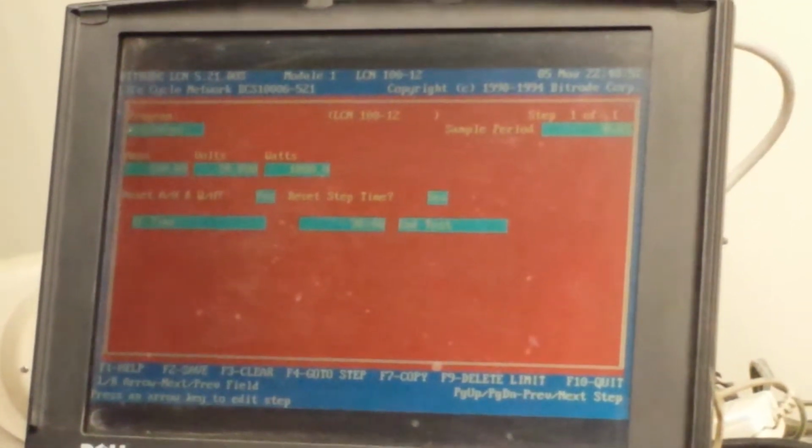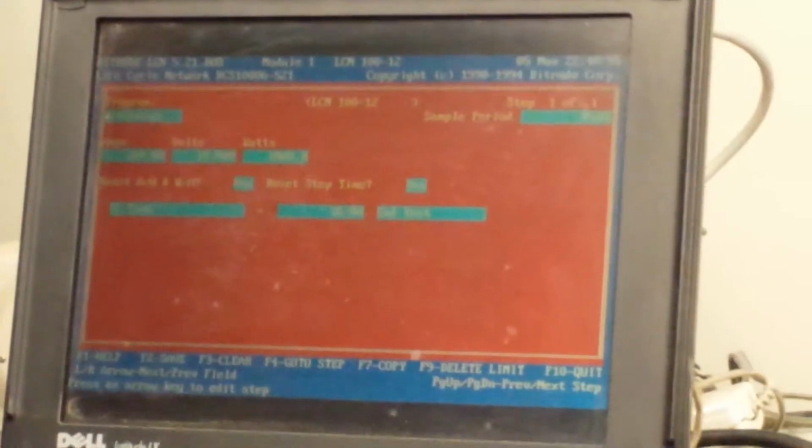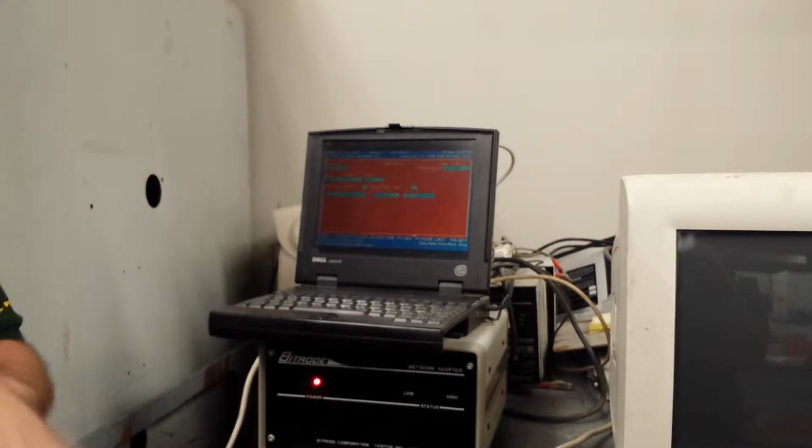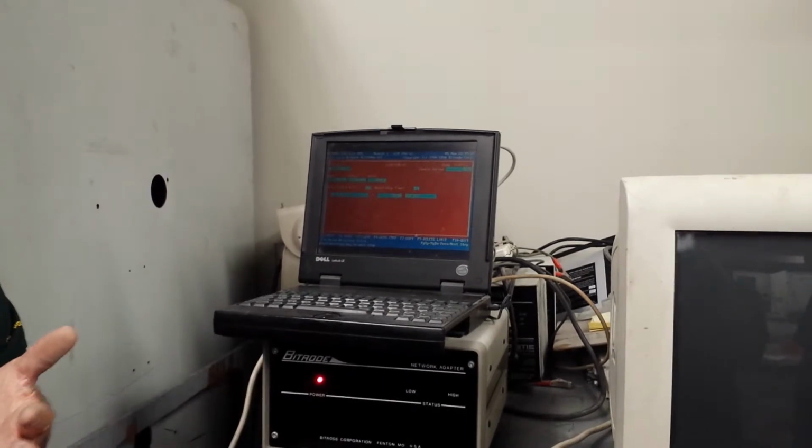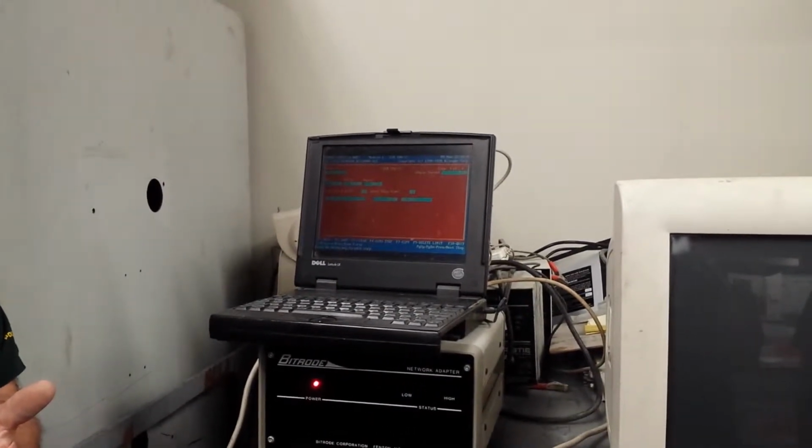If I start pulling 100 amps from a battery, what's going to be the voltage on the battery? Something less than 12 volts, right? So you can't have all three of those things at the same time because the battery won't be at 10 volts. What you're really telling this is, I'm going to make up a voltage to discharge to, and it'll limit on whichever of these three it reaches. So if you exceed 1,000 watts, it'll limit to 1,000 watts. Now we just said that we're discharging for 100 amps.